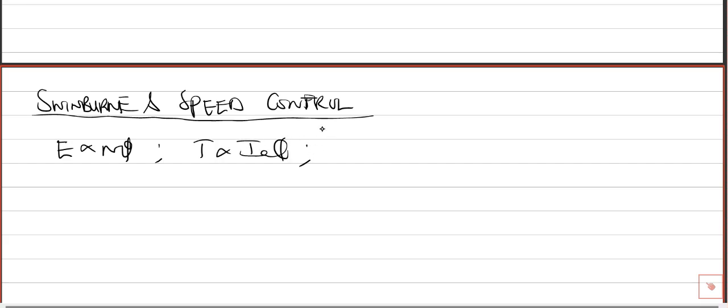If there's anything I've noticed for these calculations, it is that useful flux is always the same. They hardly bring cases where flux is not the same. In fact, they don't even make any comment about useful flux. So based on speed control, if no information is given about the useful flux, then you assume that flux 1 is the same as flux 2.